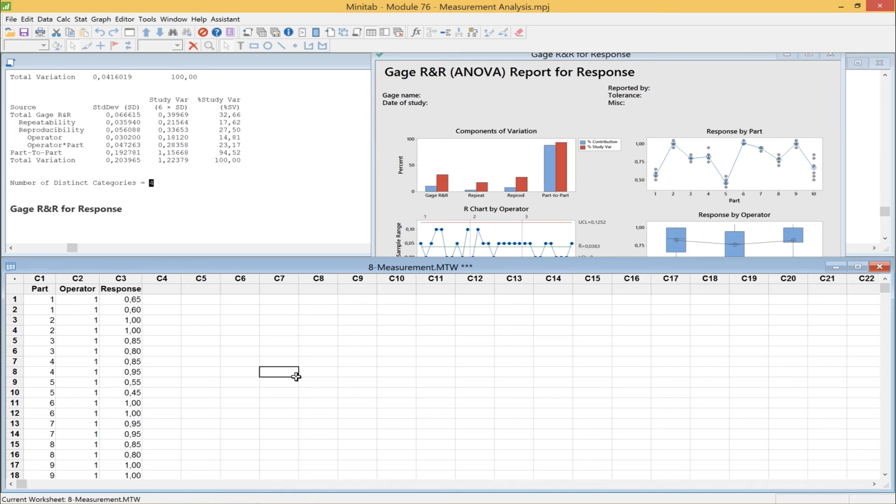So in reality, one of the things we should probably do is what we've recommended for our exploratory data analysis in our measurement system. And that is the idea of the 4-up chart, where we have the individuals chart, the capability analysis, Pareto of defect types, and then the one-way ANOVA, where we see variation for each of the different rational subgroups or steps in the process. And by seeing this, we can understand what is the problem, or where is it coming from? Is it the overall result varying? That would be the I chart, or the process capability study relative to the spec, saying it's not giving us a predictable outcome we seek?